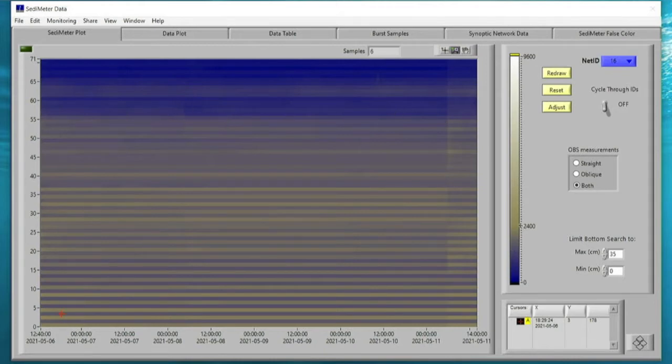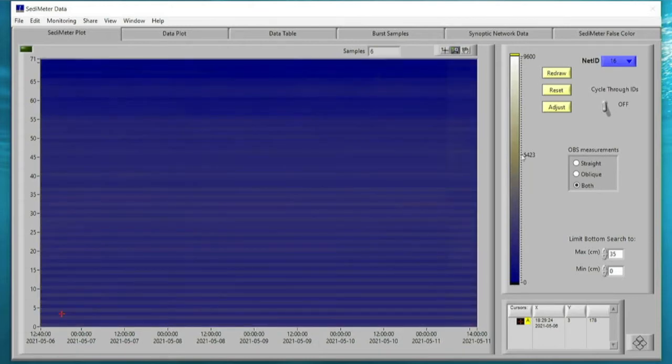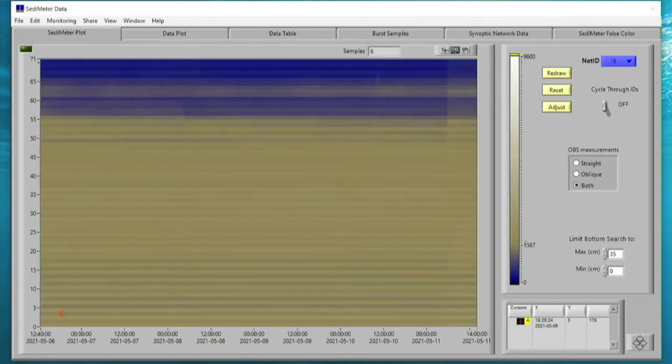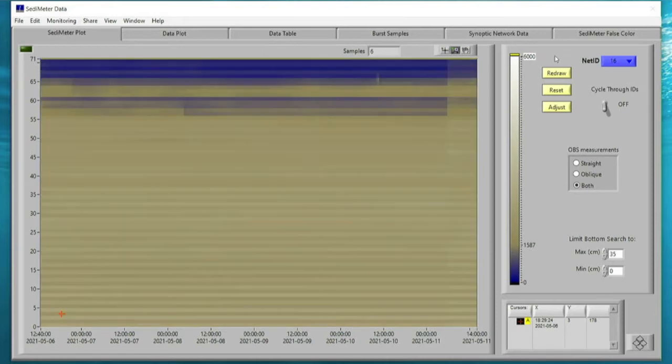You can actually use this scale here, and change the color and change the scale, the contrast. Hey, doesn't want to let me grab it now. Ah, yes. And you can change the levels here, the values, manually if you want to. Let's say we put 6,000 FTU as the max. So that way you can also add new points here, add marker, to do the contrast stretch that you want.